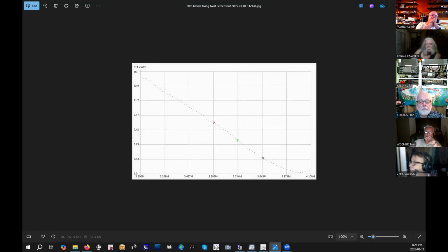Yeah, and that's a VNA. Now this model here is a little more pricey than the one that you had on your page. It's called Light VNA, and it will go up to 6 gigahertz, which is still 4 gigahertz short of where I'd like it to be, but it'll go up to 6 gigahertz. So for 1.3 gigahertz microwave, it's very handy for doing feed horns, all kinds of work that I'm doing currently. So that's my stuff. Back to you, Greg.